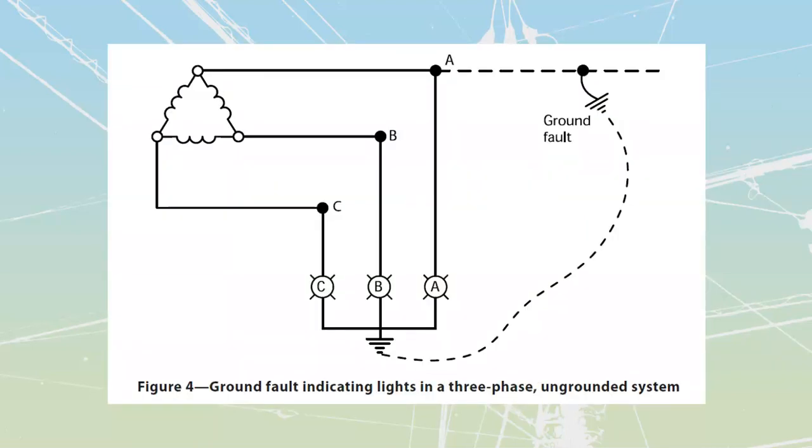Ungrounded systems on delta are a bit of a problem because when we create a delta system, there is no point to ground down that system. In essence, it's as if the ground itself exists at an imaginary point on the inside of that. And all these other lines are just kind of floating around that center point. Normally, if we don't have any sort of an issue on our lines, we're going to be completely fine.